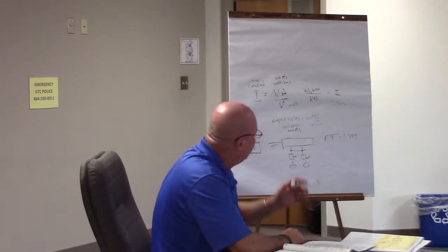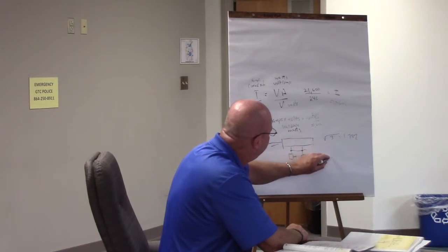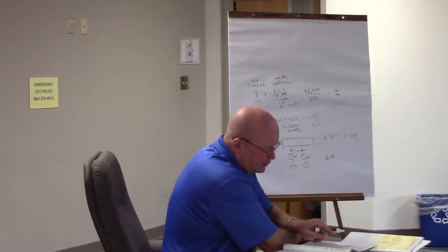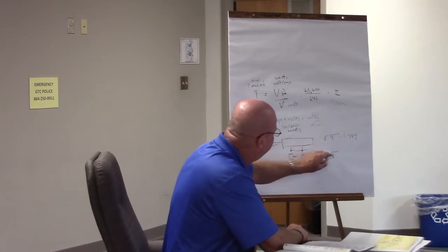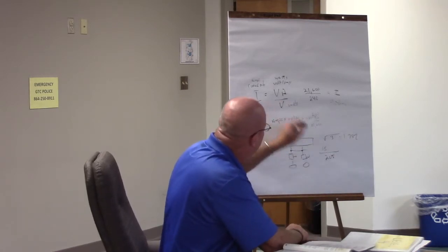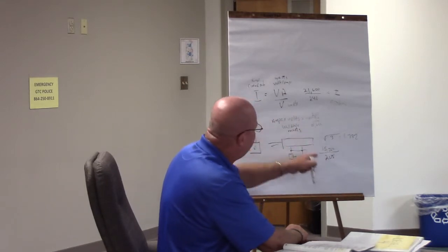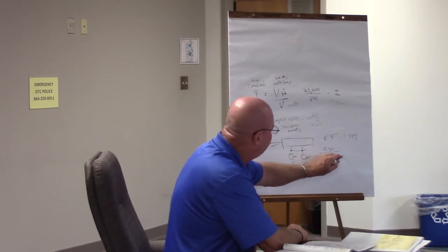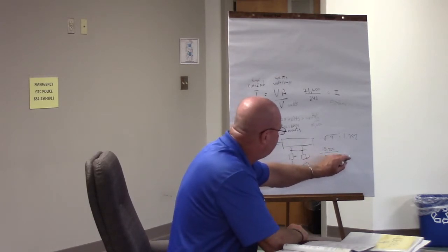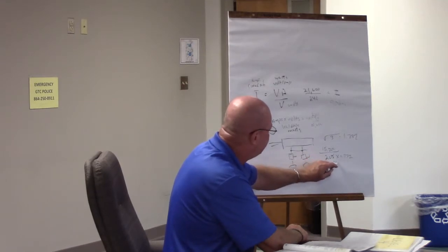It says we've got a 208 volt, 3-phase, rated 15,200 VA. We know the VA is going to go on the top, and our voltage is going to go on the bottom. But now, instead of just doing 208, we've got to do 208 times 1.732. I think that comes out to about 360.